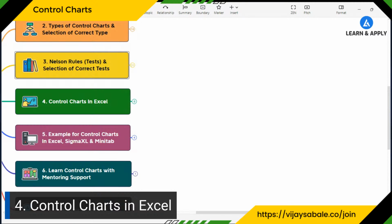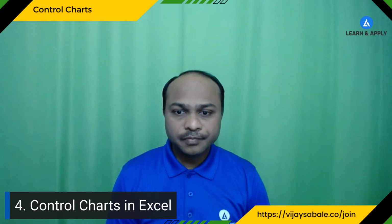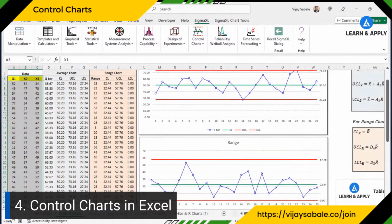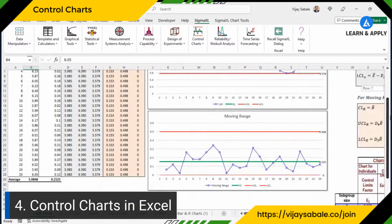Now, the fourth one is control charts in Excel. There is an Excel template that we have prepared, and you can go through that template and use it for learning these control charts in Excel. So let me share that. Yes, this is the control chart template, and it includes the 5 important control charts that we use on a day-to-day basis, like the individual moving range chart. You just need to enter the data here, and the moving range and control limits get calculated automatically, and you will get the individual as well as the range chart, the MR chart, automatically here.